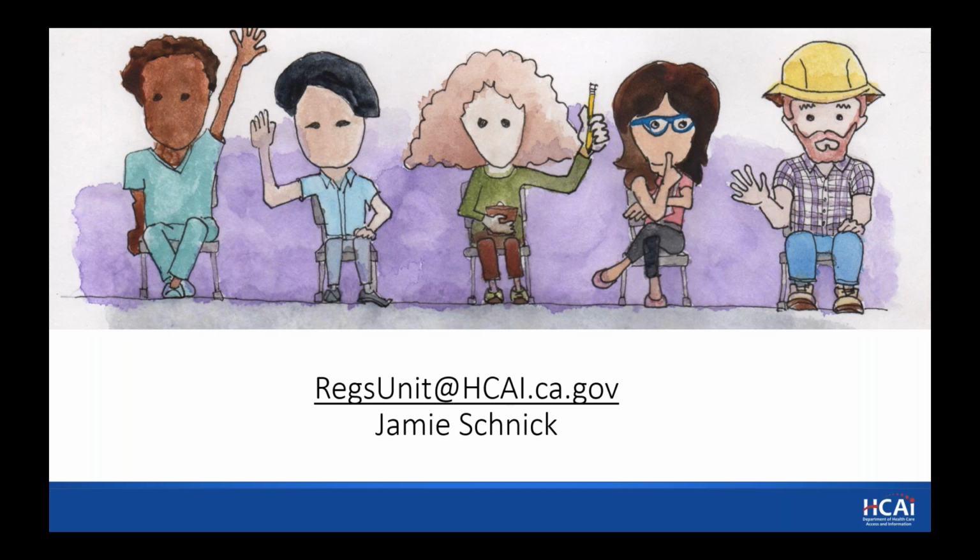Okay, so the California Electric Code 110.26E, dedicated equipment space. All switchboards, switchgear, panel boards, and motor control centers shall be located in dedicated spaces and protected from damage. Indoor, so we're talking switchboards, switchgear, panel boards, and MCCs.